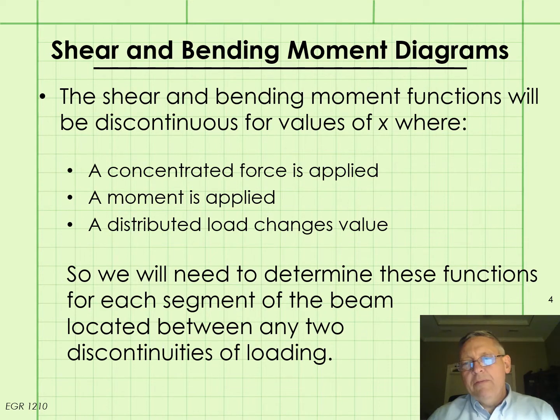Shear and bending moment functions will be discontinuous for values of X where a concentrated force is applied, a moment is applied, or where a distributed load changes value. So we will need to determine these functions for each segment of the beam located between any two discontinuities of loading.